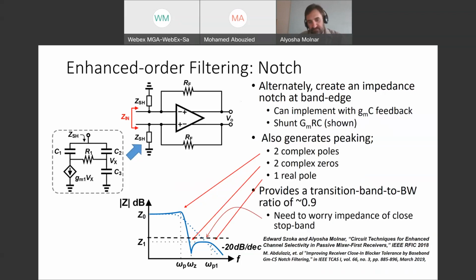The only concern here is that beyond a certain point, the filter flattens off, and so you need to make sure that flat zone is at least below the on resistance of your switches to get the best rejection you can. There's been a number of groups getting into the space lately, and this is just a sampling of what's possible. But it's definitely the case that you can do better than a simple RC roll-off on the output of your mixer and get a better filter.